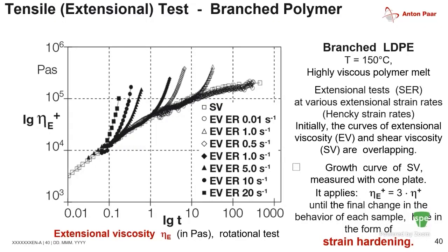You can then quantify if there's some cross-linking based on the ratio between what the viscosity should be on the linear range curve, or from Trouton's ratio for steady state, to what the peak point is in the extensional response. So again, this gives us an idea about how to look at strain hardening, which is something that you can't do from a purely rotational standpoint. So again, looking at different ways from that standpoint.